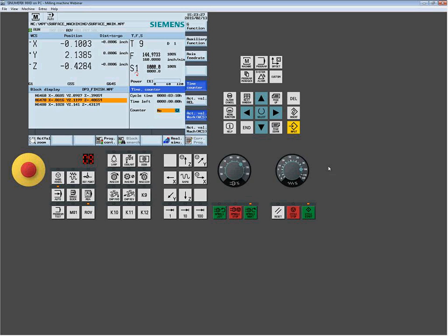You know, what tolerance is going to give me my most desirable positioning accuracy and finishing. A lot of guys think, put as tight a tolerance as I can. Well, that's not always great. A lot of times that will hurt your surface finish because you're restricting the cutter path too much, and you get a lot of imperfections in your surface.